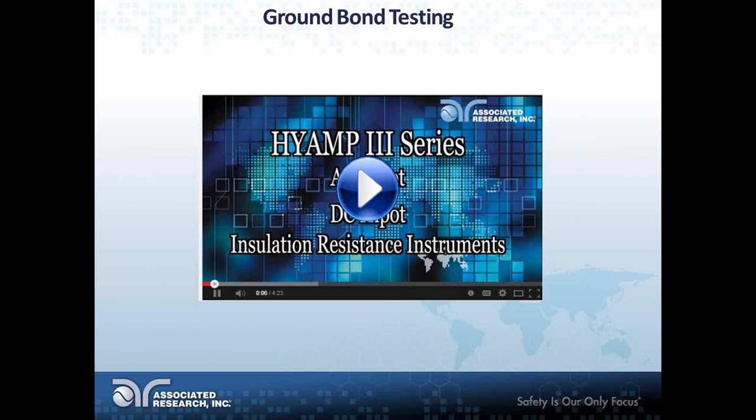All right, so glad you guys got to see that quick video clip. As you saw, what we did there is I was just showing you guys how you can run a ground bond test, and as you can see, it's really simple. You just connect your 2 points and it pumps in the current. It's taking the voltage measurement automatically and showing you the resistance value. In that case, I believe it was about 39 milliohms, which is what I expected from that circuit.